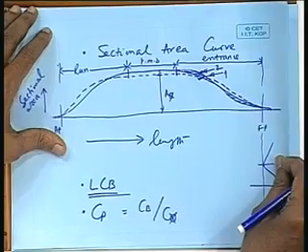So, there is a compromise between the CP you can give and the range of CP that you can give. You have to make a compromise in the range of CP that you will give. And normally for merchant ships, your bilge radius is limited to between about 1.5 to 3 meters. You do not go beyond that.